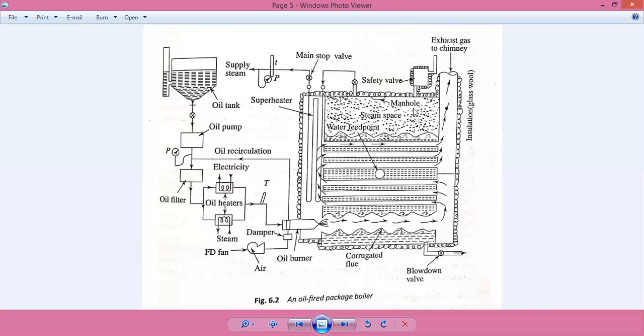But nowadays the growing need for increased quantity of steam at higher and higher pressure could not be met by fire tube boilers as per the above equation, because both high pressure and large drum diameter mean larger wall thickness. Yes, high pressure and large diameter lead to progressively thick shells, and the thicker the shell, the higher the cost.